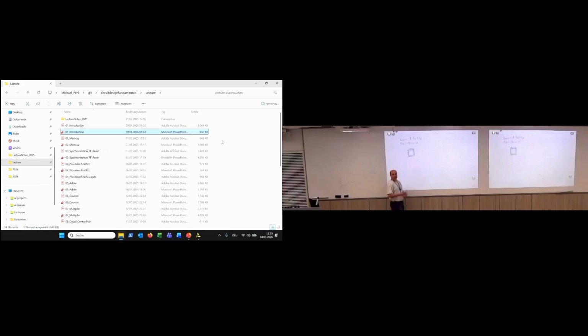This I/O ring needs to be designed so that we have VDD connects, ground connects, clock connects, and then the regular I/Os that we want to have for our logic. So this is what we have. And then we need to define, of course, how large this is. There are specific design rules depending on what your packager can do, what your process can do, and so forth. We just skip all of this, just so that you have seen it once. Okay, now we are done with this.